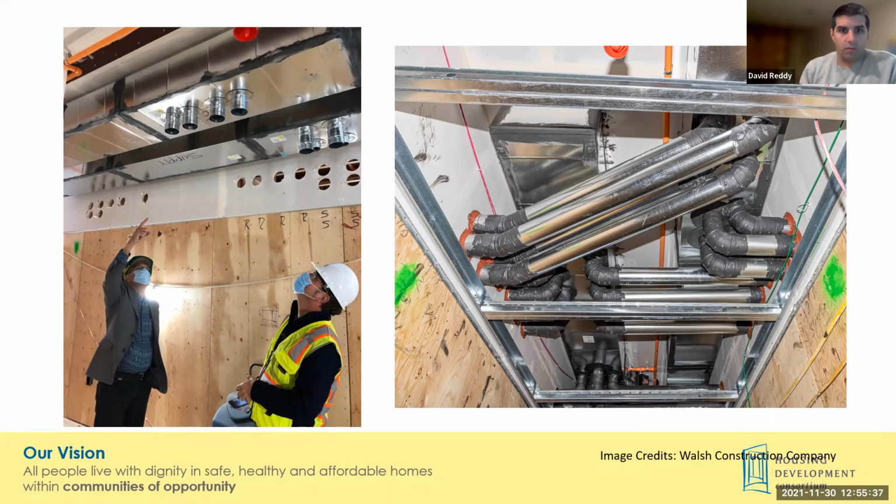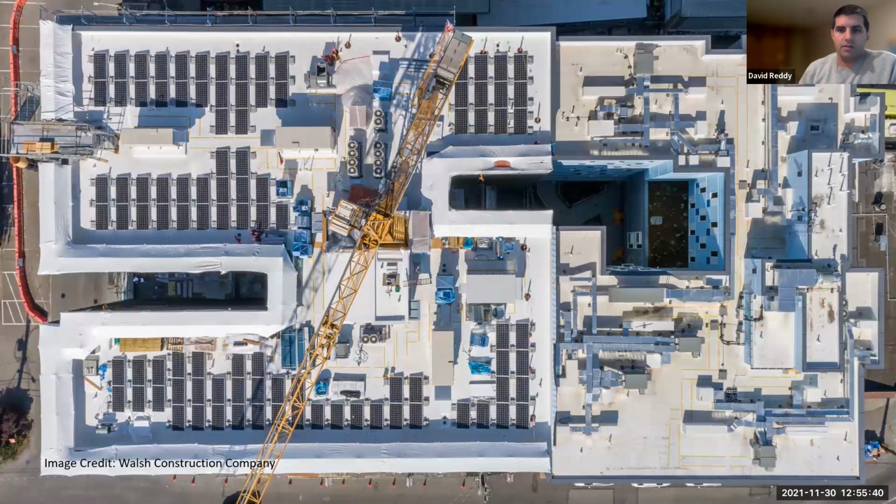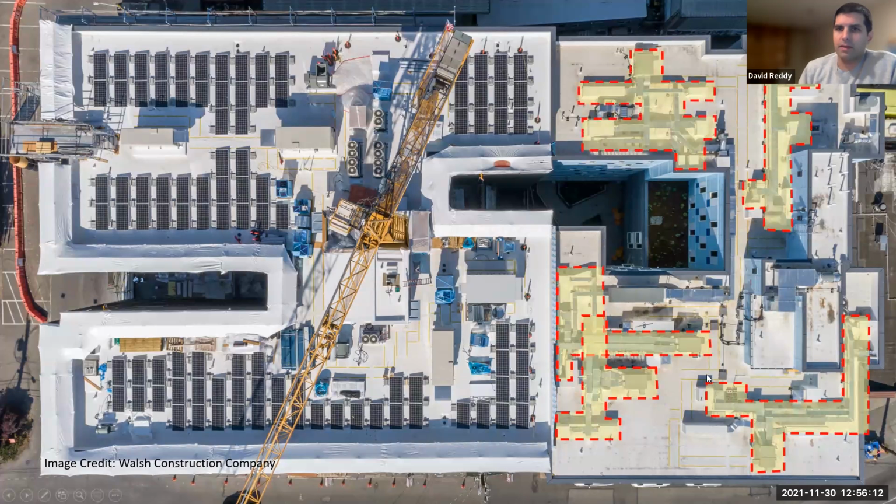The one other thing, this is an aerial view, which I think is really powerful in that it shows DSC's 2 side-by-side projects, north on the right, south on the left. The north demonstrates the approach of having ERVs distributed on the roof, but then all of that ductwork to get to the dwelling units above the roof deck, and just how much there ends up being.